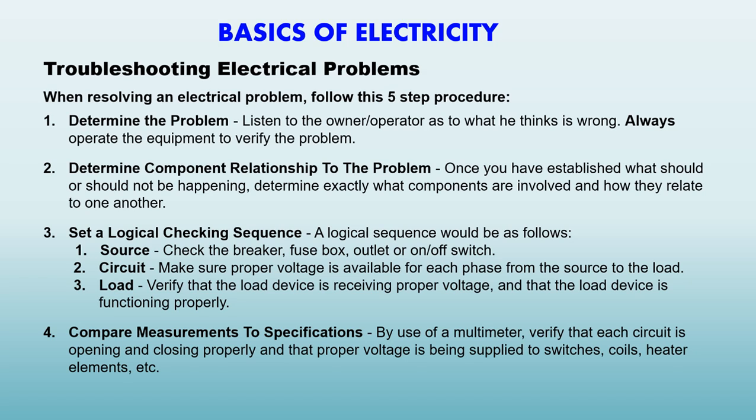Compare measurements to specifications. By the use of the multimeter, verify that each circuit is opening and closing properly and that proper voltage is being supplied to the switches, coils, heating elements, etc. Follow the problem to its origin. It's a simple process of elimination.